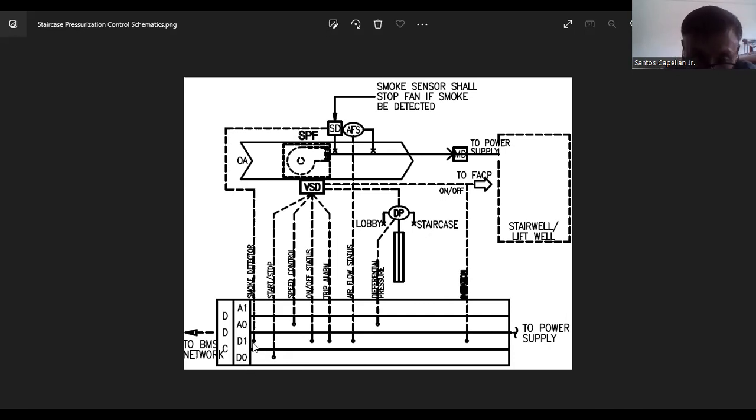If you put it in an analog input, then maybe you will have to justify why you assigned it to analog input. What is the reason? If your answer is correct, say you answer that this smoke detector has an analog control output signal, 0 to 10 volts corresponding to 0 to 100% smoke, then the person testing you will say, okay, you're right.